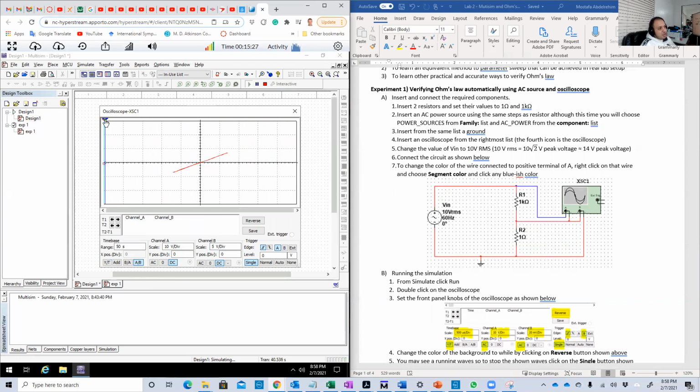How about the measurement, the slope now? Okay, basically now that's good, because now this marker doesn't point at our slope. Also, we can still read, but it's good to refer to the channels, not the x-axis, which is time. Good. Now it's referring to channels. Now, for example, at that point, look, 5.019 volt and 5.019 volt. That's bad, because the slope now is 1, not 1000.